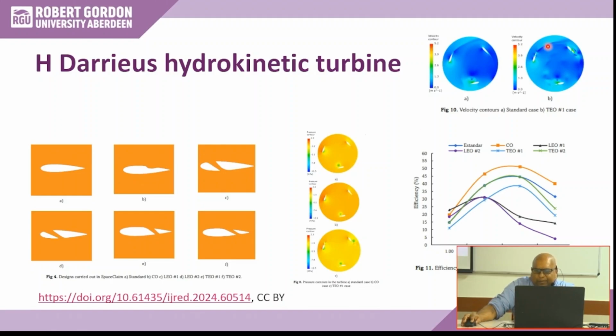So these are some of these. And then you can have a slot. And then you can have different types of slots at different locations, in the front, in the back, and things like that on the blade. These are all for controlling the flow and reducing flow separation. So a lot of techniques are there.